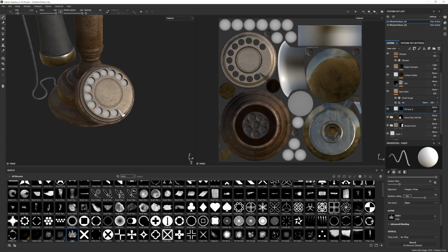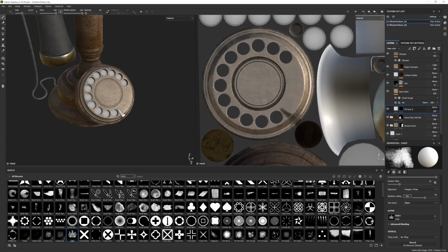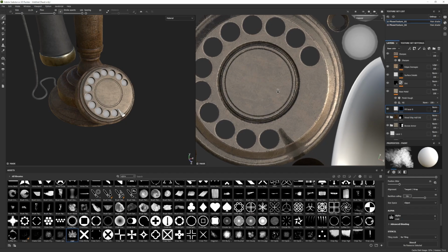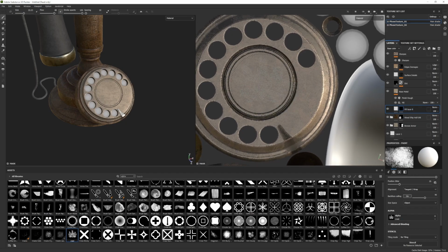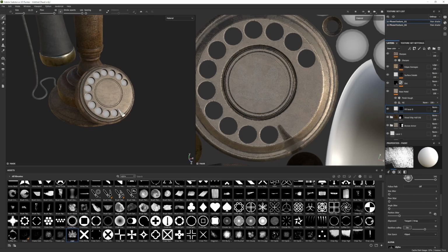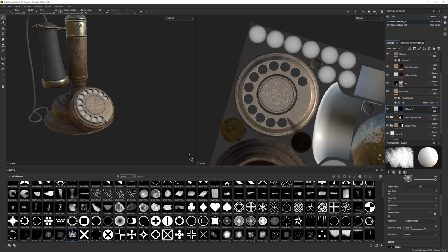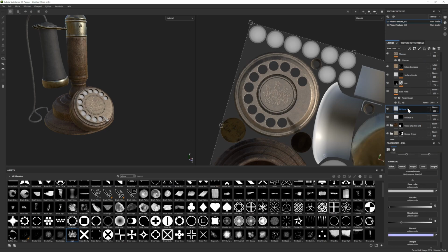And then I just quickly jumped onto Google. I just found some old vintage crest symbol on Google Images. I just saved that as an image and quickly threw that into Photoshop just so I can invert the colors to make it black and white. Then all I have to do is export that image and drag it right into Substance Painter and set that as an alpha. And all I have to do is basically go back to that fill layer, switch that to a black mask, and then just paste on that alpha directly onto that mesh.